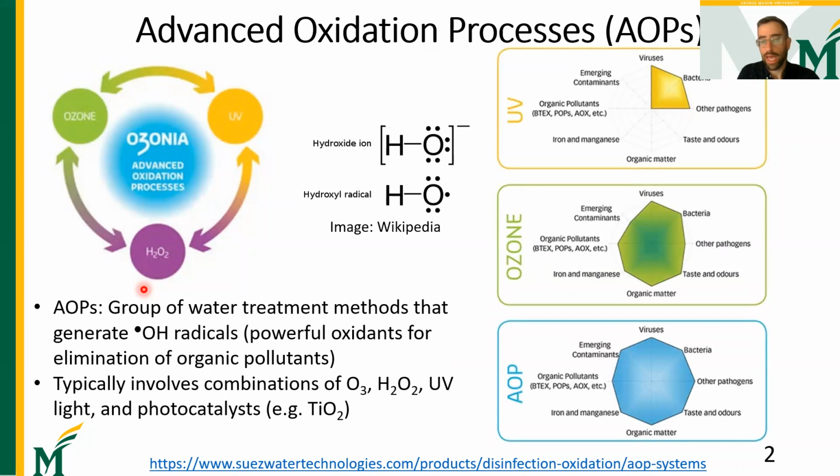And the main reason that there is such interest in AOPs is that they're able to address a wide range of different pollutants, as shown schematically on the right here. Particularly, AOPs are promising to degrade emerging contaminants or contaminants of emerging concern, CECs, which typically are toxic or carcinogenic, but survive conventional water treatments like reverse osmosis or ultraviolet light alone.